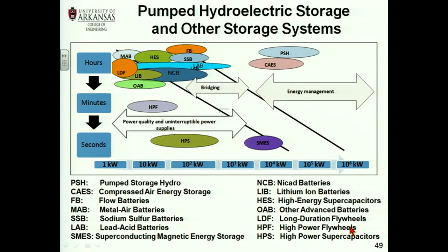Well, but there is a limit that you can go, right? You cannot make C equal infinite, because then you wouldn't have a space for anything else. So, V. What happens for the supercapacitor to provide energy? V has to drop. If V stays constant, what is the energy stored on the capacitor? It stays constant. So you're not getting any energy from the capacitor.